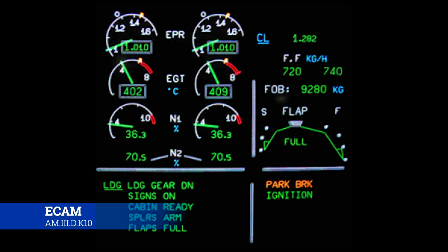And so what I always said to do, especially new avionics techs, is that you need to do the Airbus reset. Just Control Alt Delete, turn it off, let it sit, cool down, turn it back on. Half the time the fault goes away, and that's because it's made to be super computer heavy, whereas the 737 is made to be bulletproof and easily troubleshot. So you'll start to see these two differences.